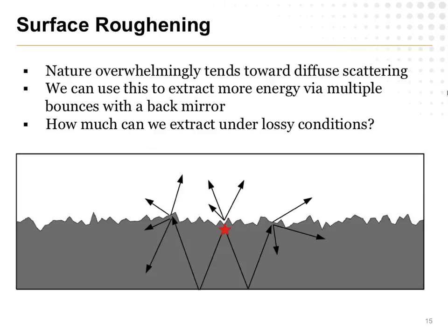So at the end of the day, what you usually will probably see is something maybe like this, where you make the top surface bumpy. So now it doesn't really matter which direction you come in and hit it from. There's no distinct escape cone anymore. There's just some probability of the photon either getting out or it'll reflect and rescatter and then bounce off the back and then reflect again. So if I have a finitely thick semiconductor here, I can, in principle, get a lot more light extraction simply by just having rays bounce around a lot back and forth and hit the surface many times over.